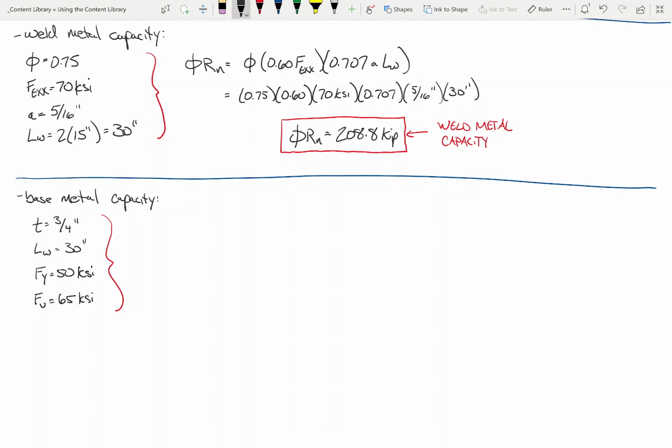So what do we not know in this expression? Can we go ahead and compute it now? What are we missing? We're missing those. Now, the first thing to point out is that because we're dealing with a fillet welded connection, they're the same. What we're asking here, everybody, is how much of the plate has to resist the shear.